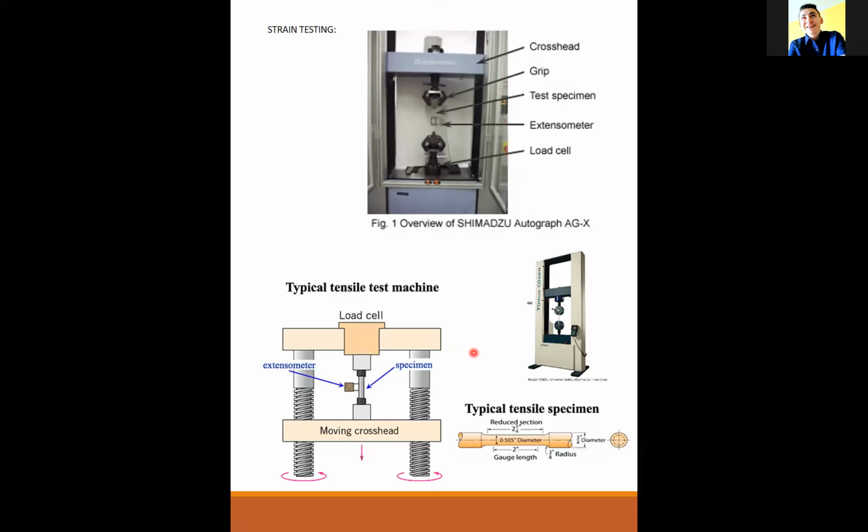Okay. And that's also why you only need one load cell. You only need to know what the load is somewhere along this chain between the action and reaction beams. There's an action beam, this is a reaction beam. And you only need one load cell somewhere in the chain, because we know that everywhere else in between here and here has to have the same action on it, or else you don't have static equilibrium.